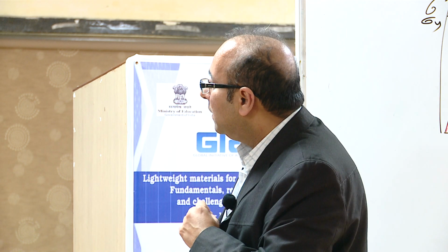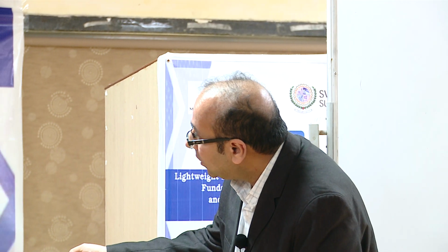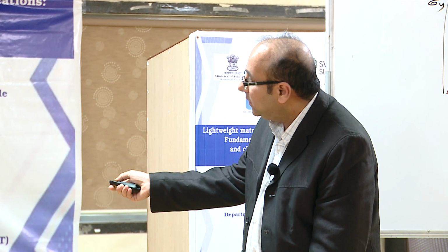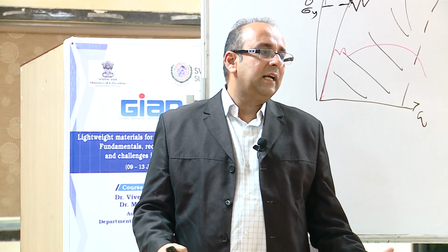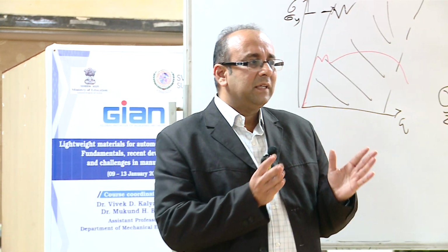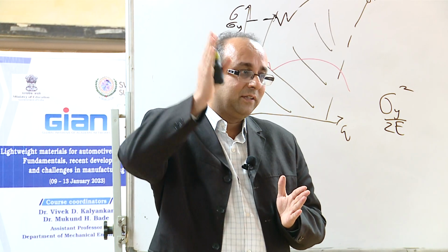Plus, this tool steel has water channels inside it. It is very important that the water should flow so that heat comes out all the time. Otherwise, I will not get martensite. I will get bainite structure. It is not that bad, but still I will not get the high strength which I want.